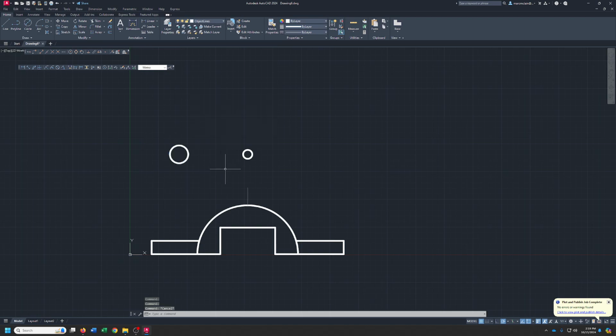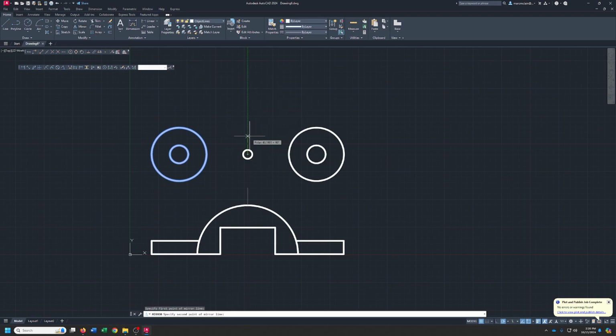Okay? So that's done. Now, we've got another one, a radius on that one. And the radius of this one is 60. And there we go. Now I can copy those two, or even better, mirror them to the other side. Remember, hit no, it erases the source object, and that was the source object. So there's that.